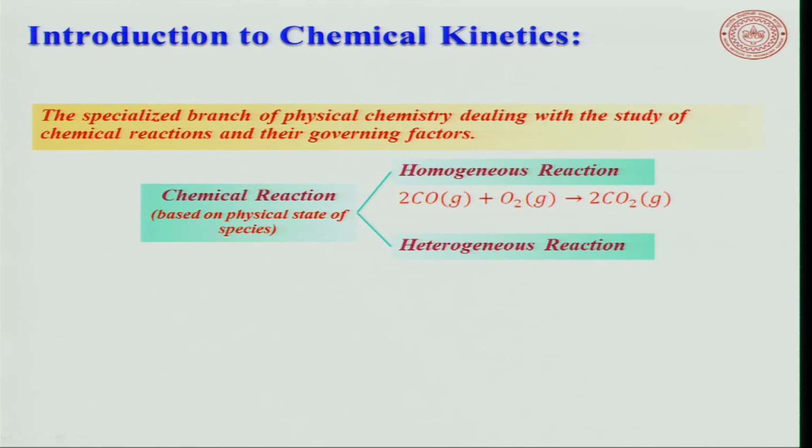Keep in mind that all are in the gaseous phase, but in propulsive devices we may need to deal with heterogeneous reactions, particularly when you are looking at solid propellant combustion, right. That means one of these reactants or even products, like soot and other things that happen in combustion, is carbon C(s) in solid form, reacting with carbon dioxide, a gas, and going into 2CO.